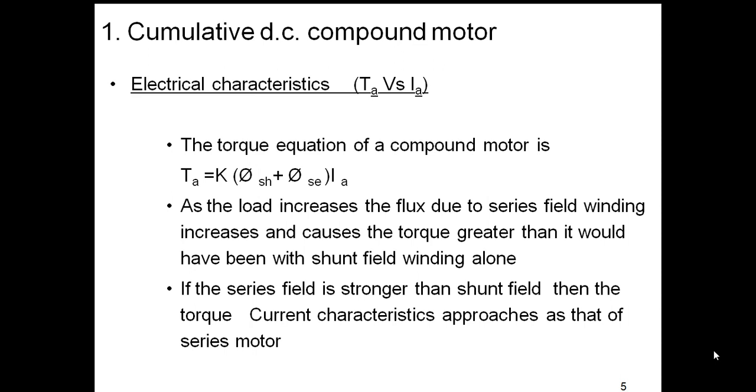And if the series field winding flux is stronger than the shunt field winding flux, then the torque current characteristics will be same as a series motor.